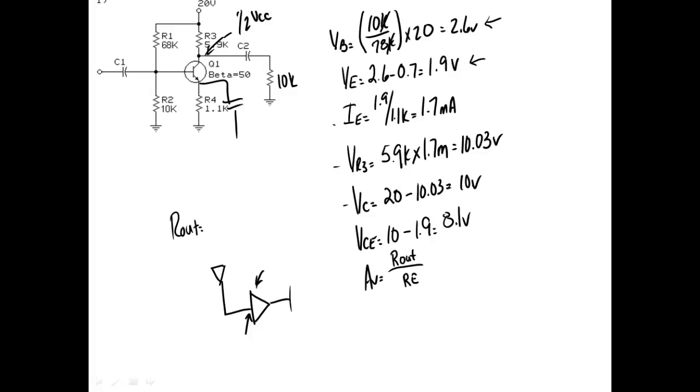Then I might run that through several amplifiers, and I start lowering my input impedance, lowering this and lowering that. Eventually when we drive our load, what do we want the output to have, high impedance or low impedance? Very low, because now it's driving a load, right? You understand? So we go through stages of amplification.